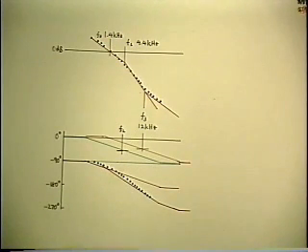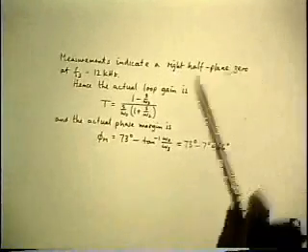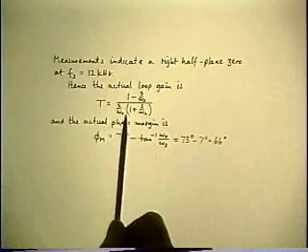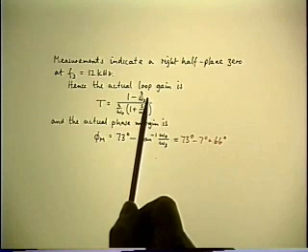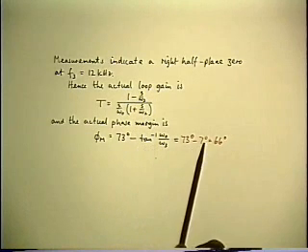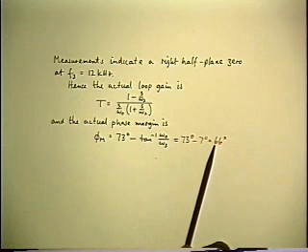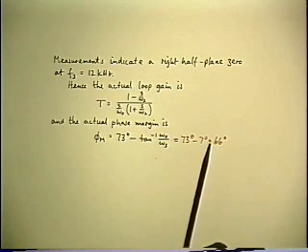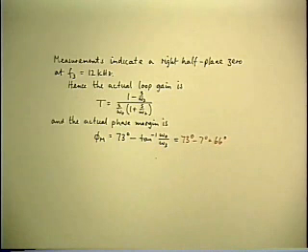So the result is the loop gain we originally thought just had 2 poles, and now we find it has a right half plane 0 as well, and it's going to use up 7 degrees of the phase margin. Well, where does it come from? Better find out now. Obviously, it can't come from anything outside the op-amp, because there isn't anything outside except a couple of impedance dividers. And there's no way that's going to give a right half plane 0. So you have to look inside the op-amp.